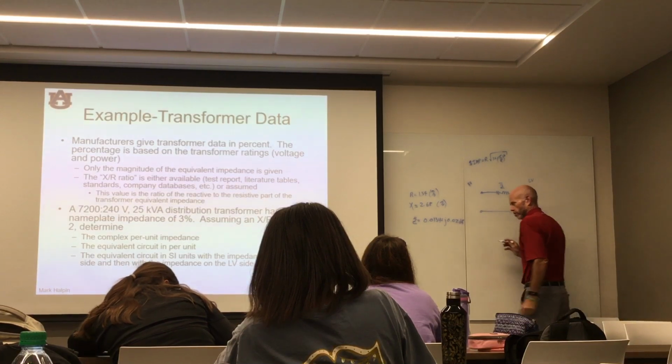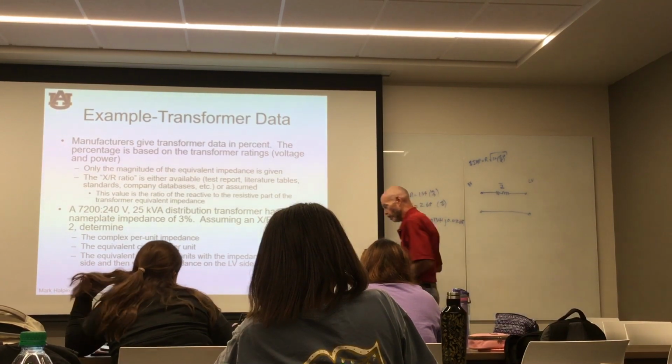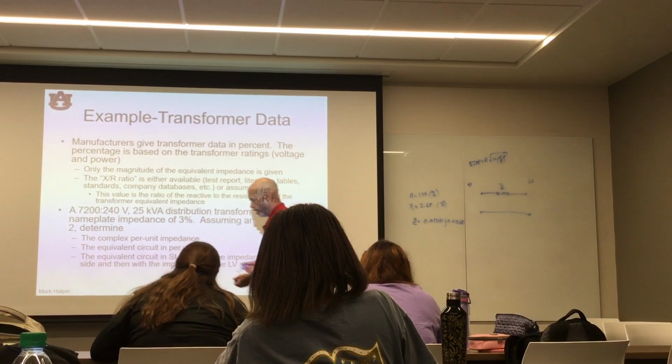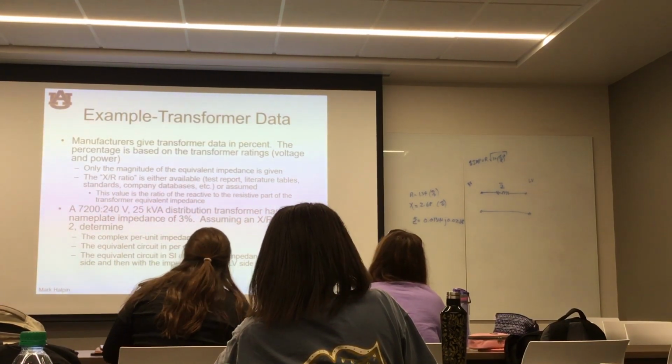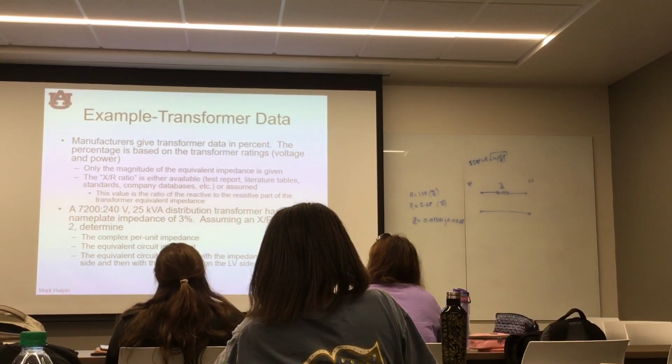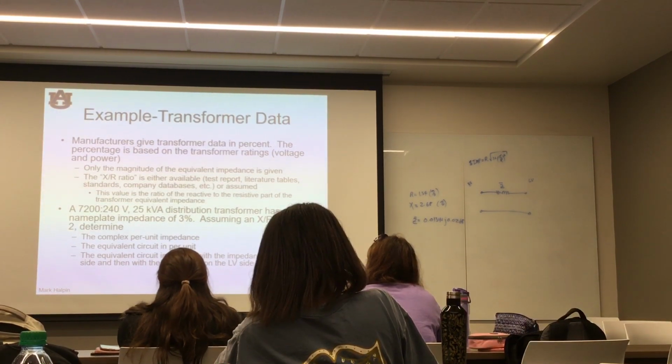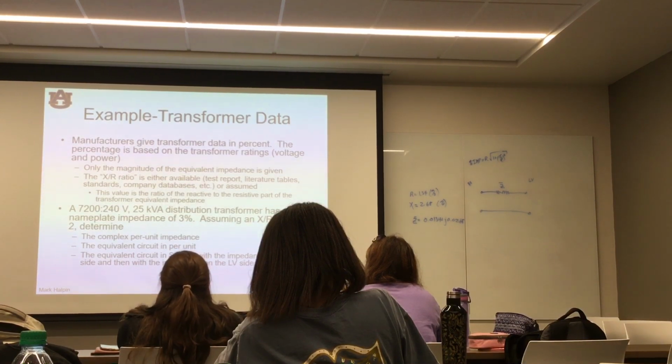But now hold on a minute. In reality, this is a transformer, right? What does a transformer consist of? Well, we've seen this little picture before. A transformer has 2 windings, and each one of those windings has some impedance. This right here represents the ideal transformer, and these are its impedances.